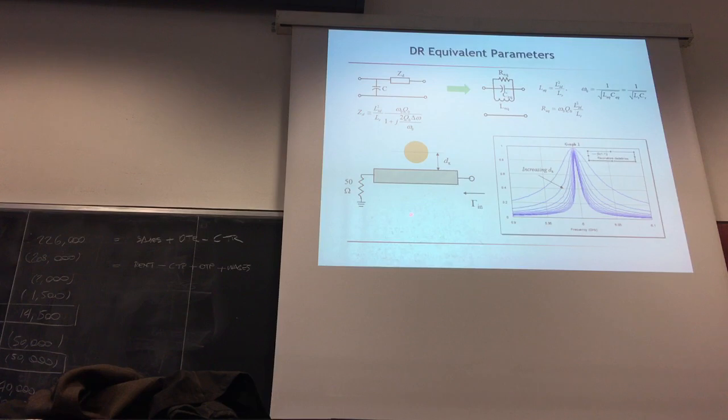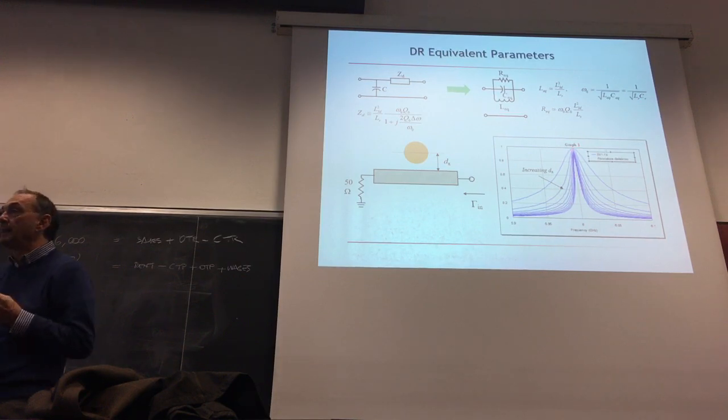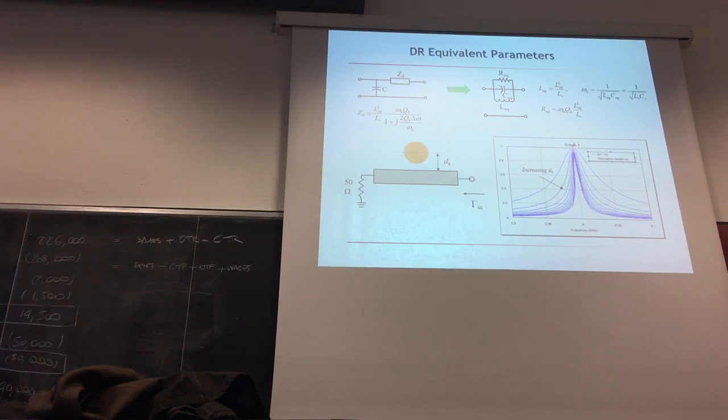For instance, making a simulation of this configuration, varying the distance dx between the electric resonator and the microstrip, and observing the reflection coefficient at the input of this line, it can be observed that just around the frequency where the resonator resonates, we have a reflection coefficient which is in magnitude quite close to 1, which means open circuit. All the power is reflected back.